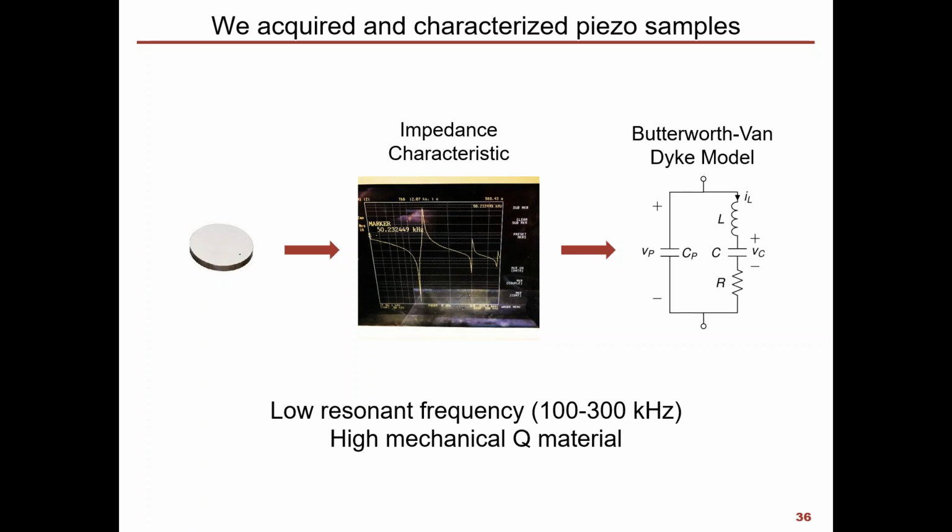Yeah, that's a really good question. We have not personally studied the reliability over time of this yet, but that's a really important question going forward to make them practical. When a piezoelectric resonator is fabricated, it is put through what's called a polarization process, where we expose the material to very high voltage. In that process, we make the dipoles align in one direction.